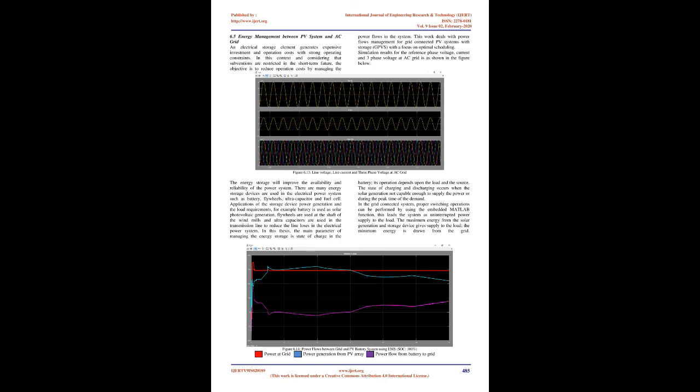When the battery current is negative, the battery will recharge following a charge characteristic as shown below in the figure. The exponential voltage increases when the battery is charging, no matter the SOC of the battery. When the battery is discharging, the exponential voltage decreases immediately. Figure 6.7, Discharge characteristics of battery module.